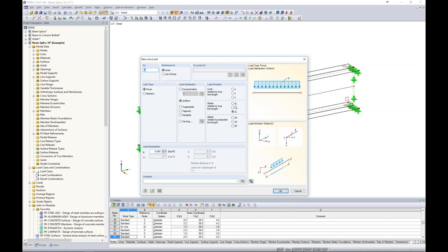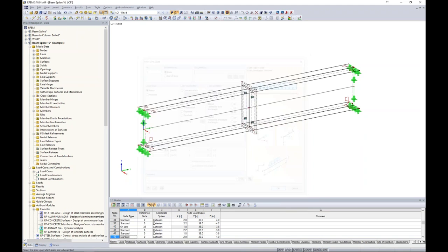So with a line load, we simply specify the load direction in the global ZL direction and give it a magnitude of -50 kips per foot. I click OK, and then I can click to the top of that beam member over here on my left. Now, I think it's perfectly acceptable to maybe not have symmetric loading for this particular connection, but to really see when we have unbalanced loading. So I'm just going to apply my load to my left-hand side and leave the right-hand side without any load except for self-weight.